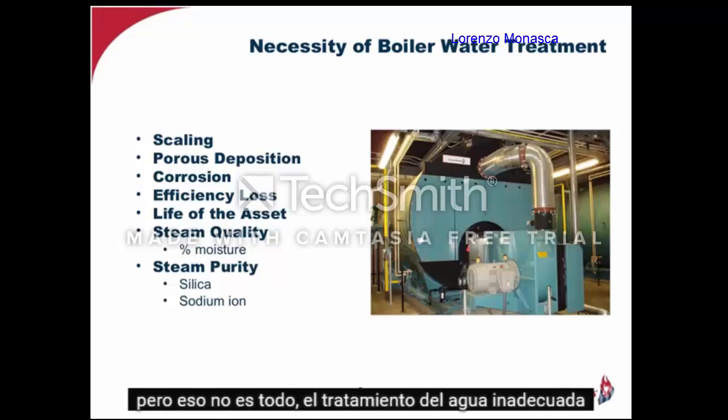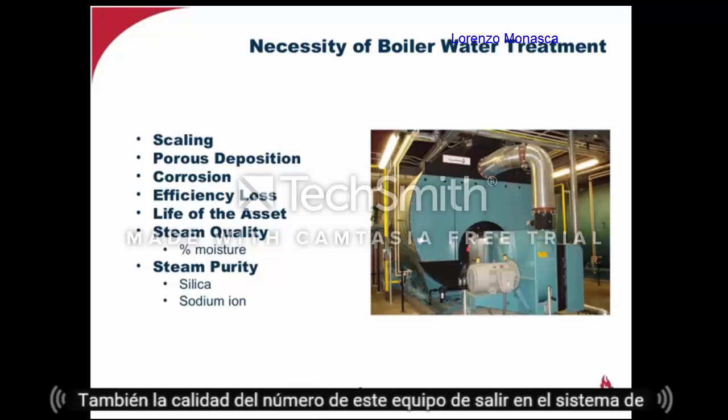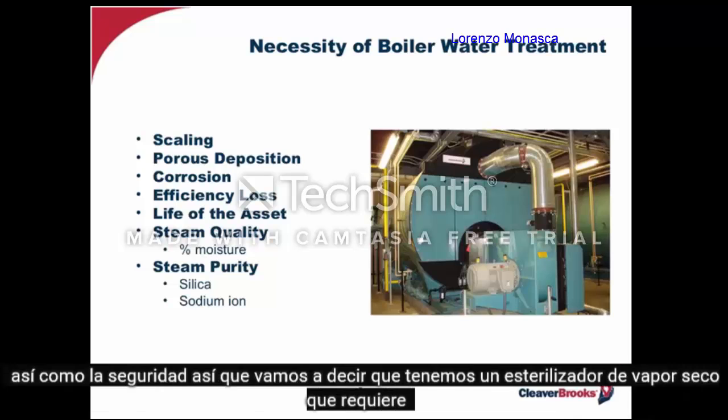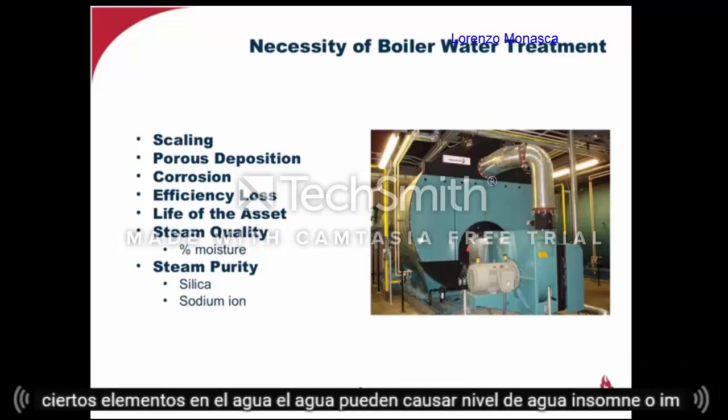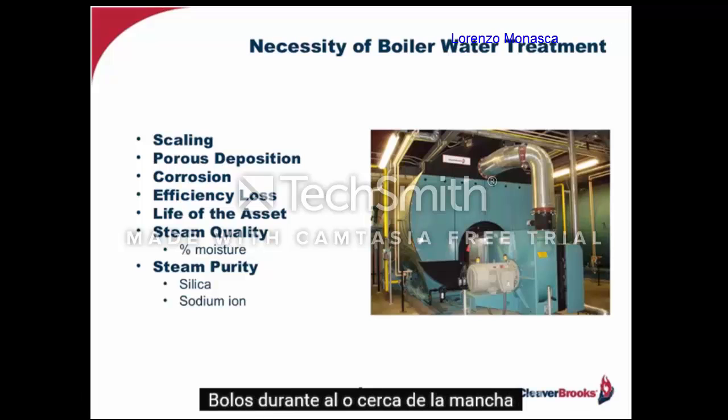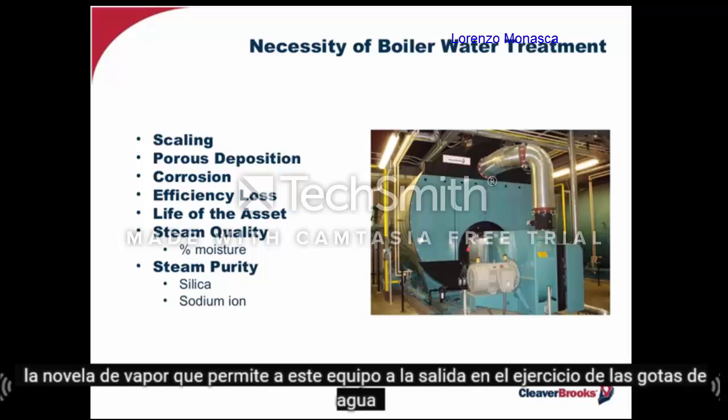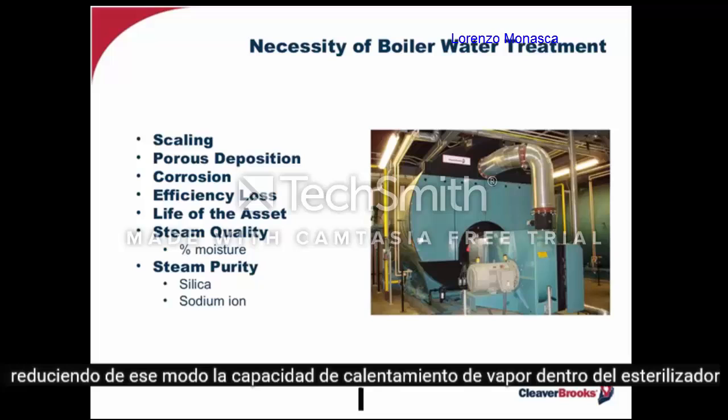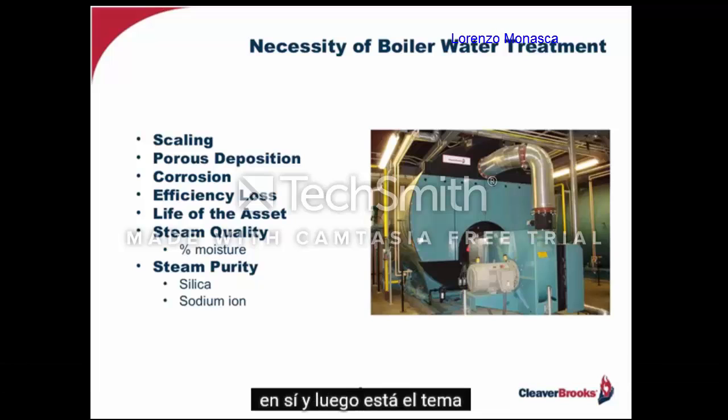But that's not all. Improper water treatment also affects the quality of the steam going out into the system as well as its purity. So let's just say we have a sterilizer requiring dry steam. Certain elements in the boiler water can cause an unstable water level or foaming to occur at or near the steam nozzle, allowing the steam to exit while carrying water droplets within it, thereby reducing the steam heating capability within the sterilizer itself.